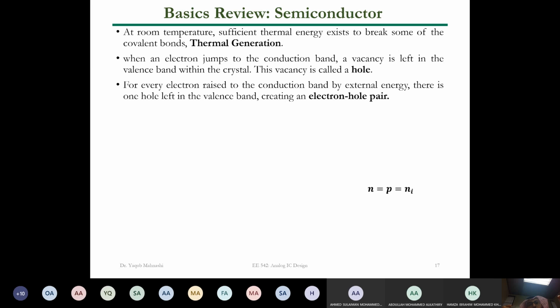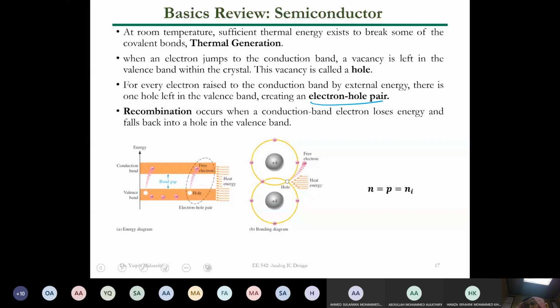Once it is exposed to some thermal excitation, now the electrons will move and the holes will be created, and that's why we have what we call electron hole pair generation. And all of this, Shabab, the recombination between them, all these details are not needed by now, but I need you to have a kind of bird's-eye view of the semiconductor, what is going on inside. The atom by itself is in an equilibrium state. When you bring thermal excitation to it, meaning heat, the electrons move.